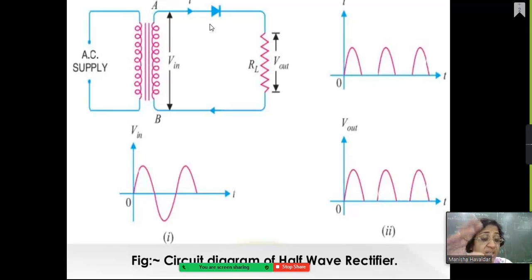If it has to conduct, it needs a lot of voltage for that, and we don't provide that much voltage. So we say that it is in the inactive mode or non-conductive mode, and therefore here you can see that in this other half cycle, that is in the negative half cycle, or for negative input voltage, current is 0. Similarly, the voltage will be 0. So this gap will be present over here.